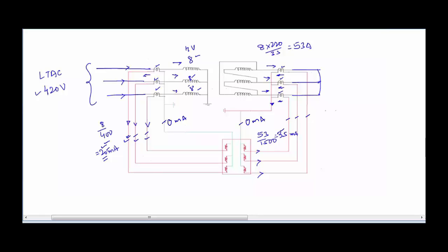So we are going to get all these readings for this particular transformer, means the transformer whose MVA rating is 80 MVA, whose voltage ratio is 220 kV by 33 kV, and of course its percentage Z is 5%. I have taken 5% as the percentage Z of the transformer just for the sake of simplicity, but for a power transformer whose MVA rating is 80 MVA, and whose voltage ratio is 220 kV by 33 kV, or even 132 kV by 33 kV, the percentage Z normally lies in the range of 15% to 20%.